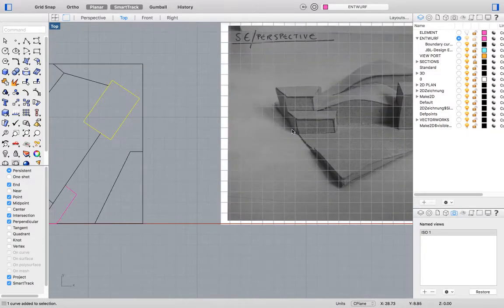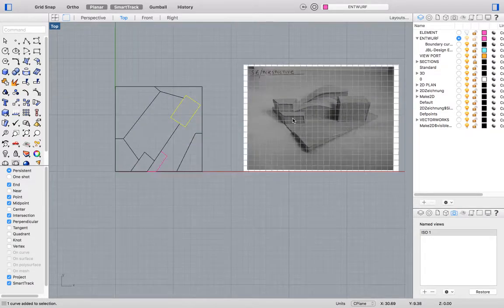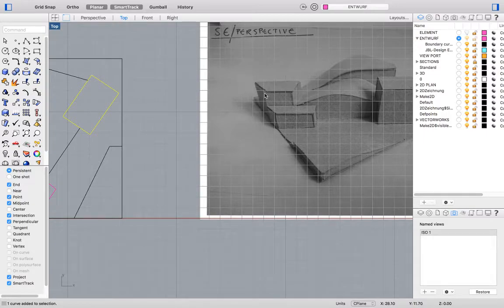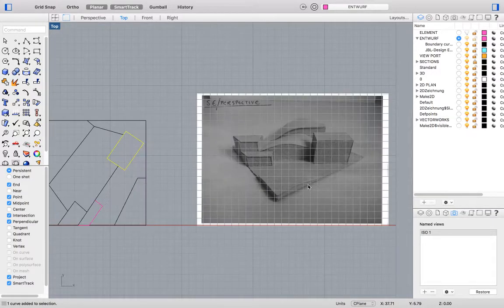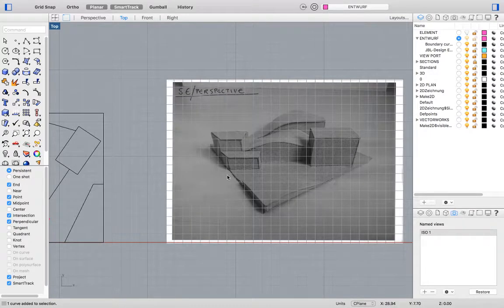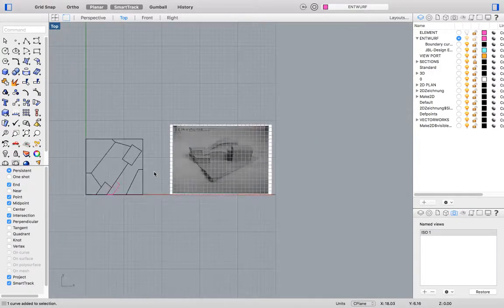Okay, I know the model heights of here, so I know that this is 15 millimeters, this is 30 millimeters, and this is 35 millimeters high. But we know now that we're in meters scale, so I can now say that this is 3 meters, this is 1.5 meters, and this is... sorry, this is 3.5 meters. This is 3 meters, and this is 1.5 meters. So we're going to make an extrusion of those heights in our model.